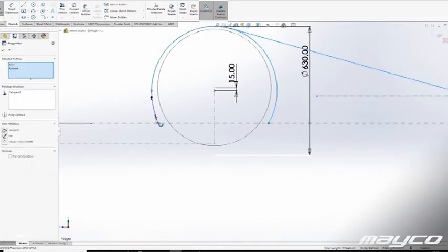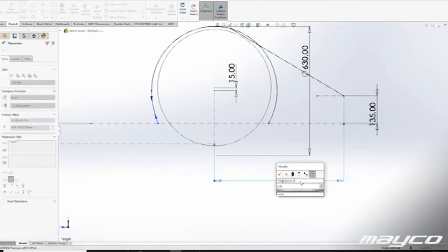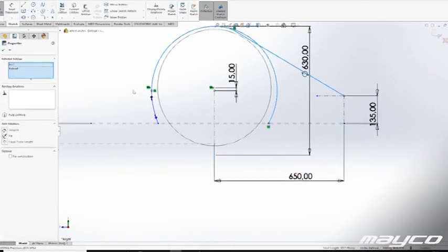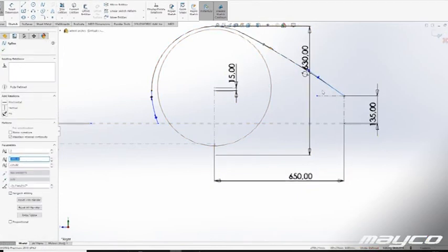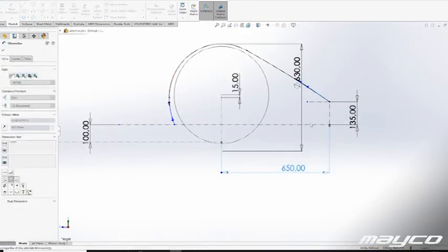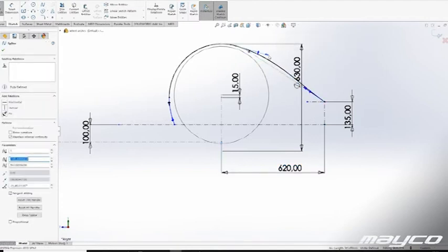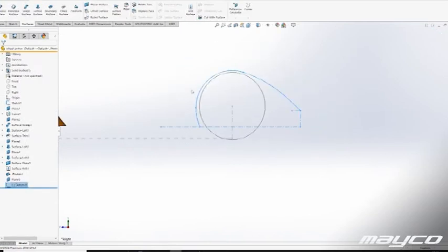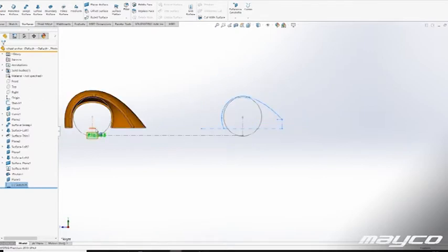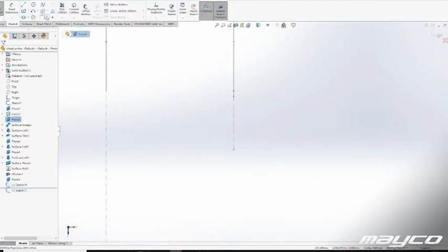Now, why would you want to convert a part or a surface to a solid body? Well, a surface is basically nothing and you cannot do anything with it, and if you make it into a solid body, you can maybe 3D print it, or you can do something with it. So if you want to do something with your surface model, so for example you want to make a mold out of it, you need to go into solid bodies.